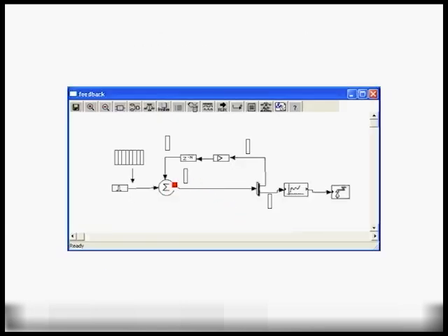In the case where we have feedback, though, the add block can't consume all 128 samples from the impulse block because it only has one sample from the delay, feedback delay block. So in this feedback loop, we only process one sample at a time. So this is a concern for efficiency. Even though we have 128 samples available on this port of the buffer, we only have one sample over here at a time. So this is one thing we need to realize about feedback.